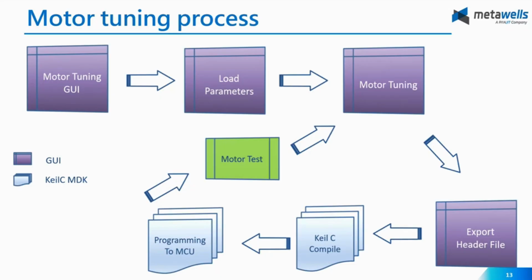Second step, load parameters. We load the motor parameters into the GUI, such as resistance and inductance, to establish the starting point for tuning.